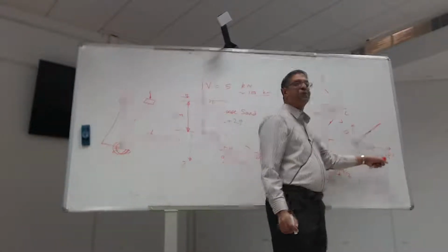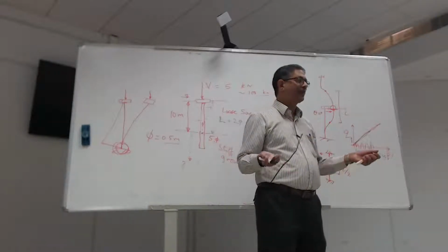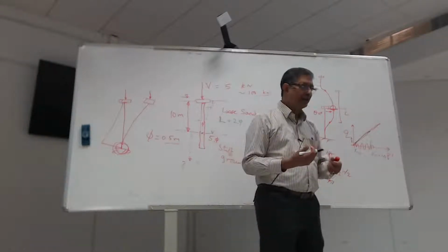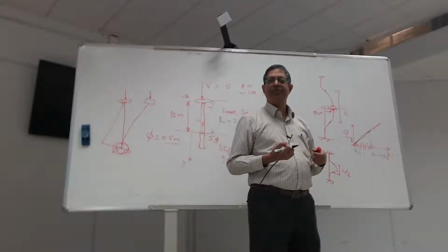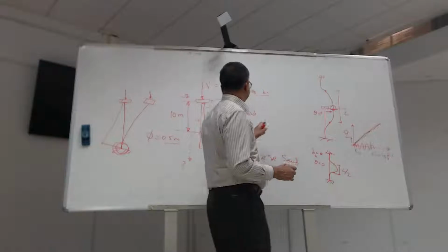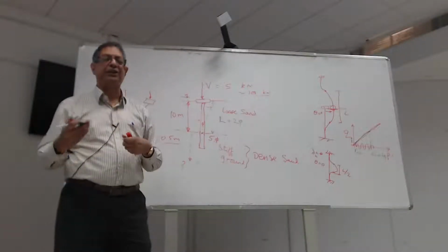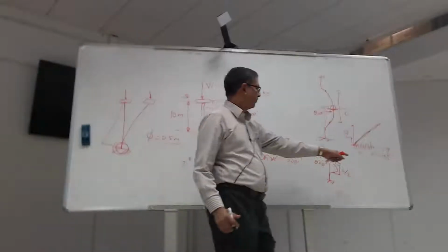How can it increase its p'? It can't do anything about the total stress. Total stress is what it is. So the only way it can do that is by creating suction. So the pore pressures in the region of soil here must be falling to create a suction to satisfy this.